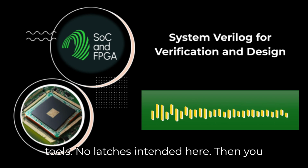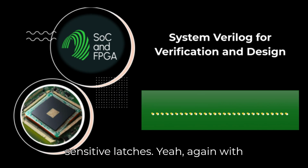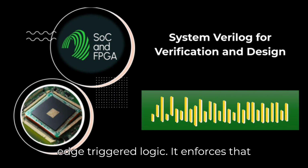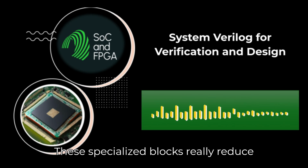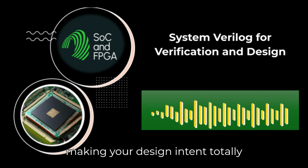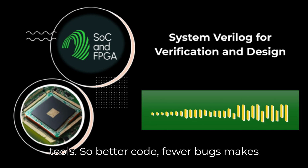Plus, it tells synthesis tools, no latches intended here. Then you have always_latch, specifically for level-sensitive latches, again with inferred sensitivity. And for flip-flops? That's always_ff. It's for synchronous edge-triggered logic. It enforces that assignments happen only on clock edges. These specialized blocks really reduce bugs by enforcing stricter rules and making your design intent totally explicit to both humans and the EDA tools. So better code, fewer bugs.